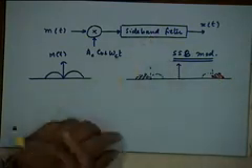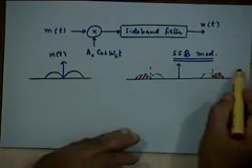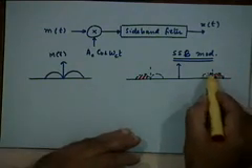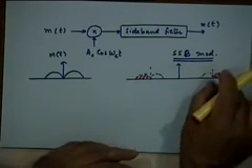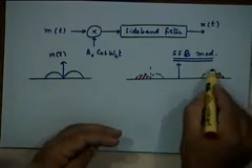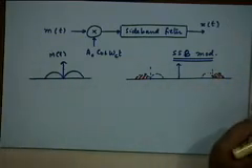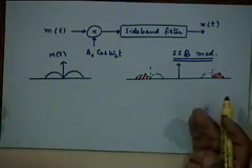What kind of a sideband filter should you have? A high pass filter, right? Or we could have a band pass filter here, which will only pass this portion of the spectrum and reject everything else. Theoretically a high pass filter will do; in practice we'll of course use a band pass filter.